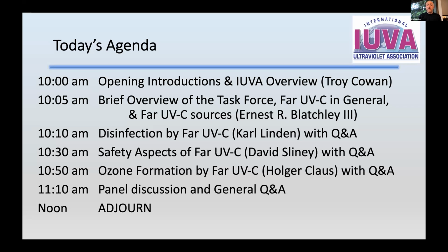the layer of liquid will have some absorbance to it, but that absorbance effect on the ability of the photons to penetrate will be quite minor if it's a very, very thin layer. If it's quite a thick layer, if we're talking about millimeters of depth, then we see certainly blocking of UV photons getting into the heart of that aerosol and inactivating the pathogen. So that's something we need to look at a little bit more closely with some modeling. But what we know right now is that the thin layer that occurs around pathogens in an aerosol is so thin that it doesn't block the photons appreciably. That needs to be looked at a little bit more in different types of matrices, but there are those two factors: the absorbance of the layer as well as the depth of that layer, and the penetration of the photons will be affected by those two factors.